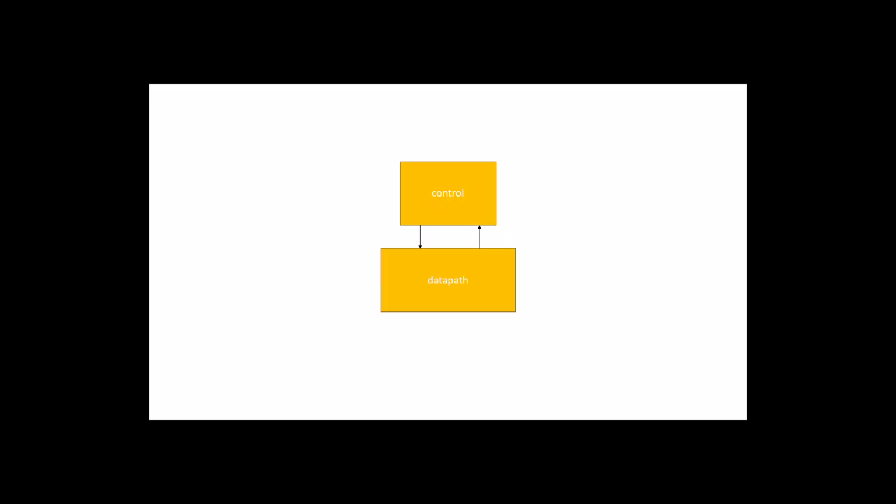Separating data path and controller helps because data paths use regular and specialized circuits, while controllers can take advantage of logic and physical optimizations during synthesis. We can change what the machine does by changing the controller FSM, the operations and registers on the data path, or both.